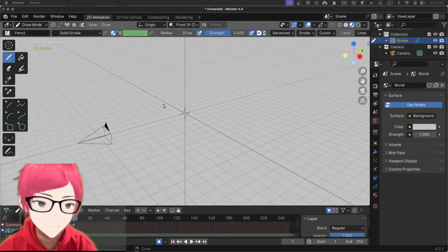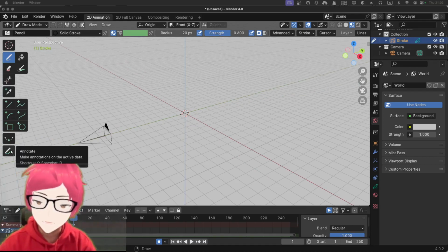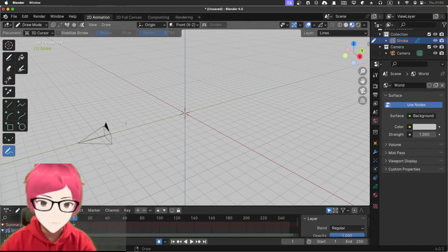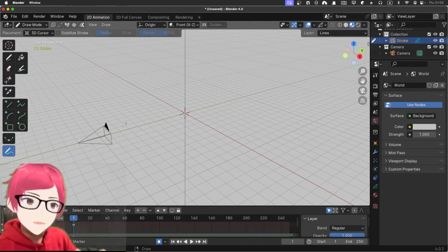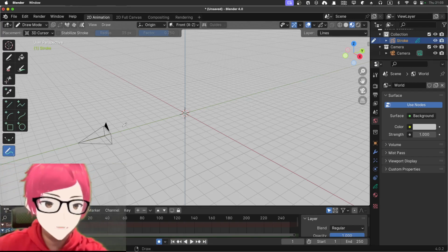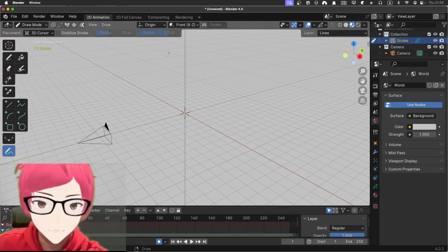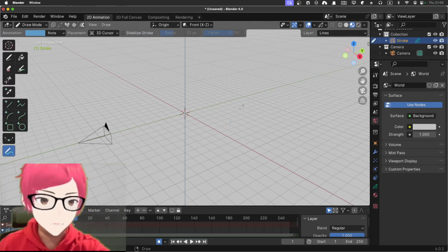Right now, for this plane, let me use this annotation. Annotate, you can use Shift and Spacebar, and then press D, which is a shortcut for annotation. Once you click this annotation, you move a little bit closer, and I can just draw this annotation here. Okay, it's just some bug with my pen.